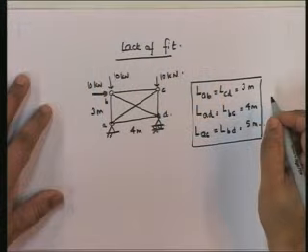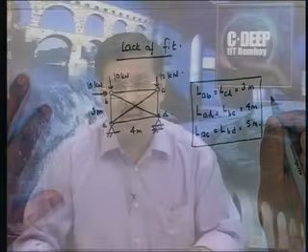So you have to cut them up so that you get exactly the sizes that you want. There is also the factor that what we call a 10 meter length may not be exactly 10 meters. So even though we want AB and CD to be 3 meters, AD and BC to be 4 meters, and AC and BD to be exactly 5 meters, in reality, when someone actually cuts the members and puts them together, you might have a situation where some members are not exactly the size that they are supposed to be.